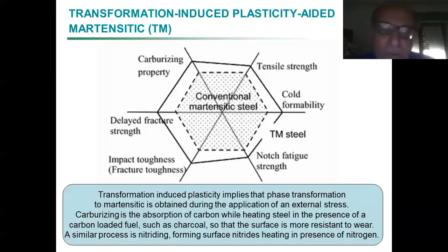This is a quite old treatment. Now it's much more performant with nitrogen, to prepare steel in an atmosphere filled with nitrogen, and therefore allowing the nitrogen to enter the surface, providing you with higher hardness.